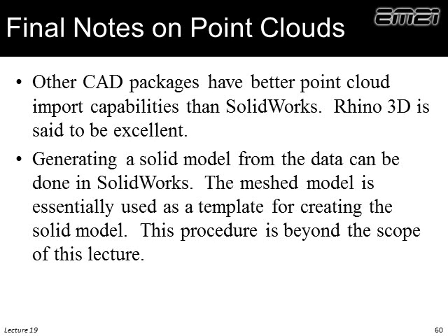The other thing, even though we can create a surface mesh in SolidWorks, it's not really an editable object. But the purpose for that is that you bring in a point cloud and it just stays there visually, and then you model something manually that fits the shape of that. Anyway, the whole procedure there I think is beyond the scope of this lecture, but suffice to say that when you mesh it in SolidWorks, it's not an editable object. It's really just there to serve as a template, and you sort of trace your model around it, if you will.